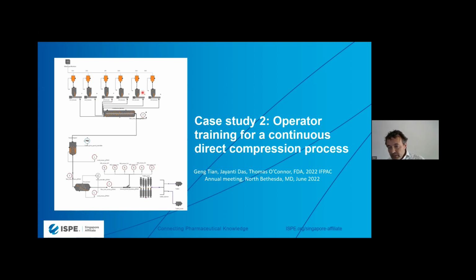But it also allows us to better understand how all these fluctuations propagate through the system. And if we have too much residence time distribution, and we have a problem and we have to do a recall, then you may have to recall many, many lots. So you don't want a residence time distribution that is too broad because that's not good for product traceability. If your residence time distribution is very narrow, then your process may suffer from robustness issues.